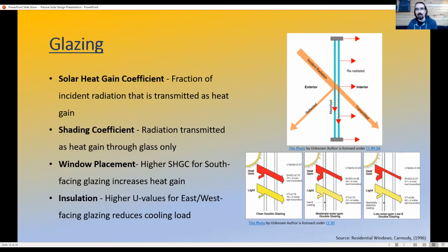This is also one of the areas that you can run into a lot of high costs for passive solar design. The better the windows you want to use, the higher the cost is going to be for your project. And there are a lot of different types of glazing options out there. I've looked at a couple down here that are typical clear double glazing, or a double glazing with a coating, or a double glazing with a gas. And we've seen low E windows and argon filled windows that transfer heat at different rates. If you start getting into triple panes and insulation, you can really add a lot of cost to the project, but it does come out in the long run. If you design properly, based on the amount of energy that you're using, you can have some energy savings that pay off those windows in the long run.